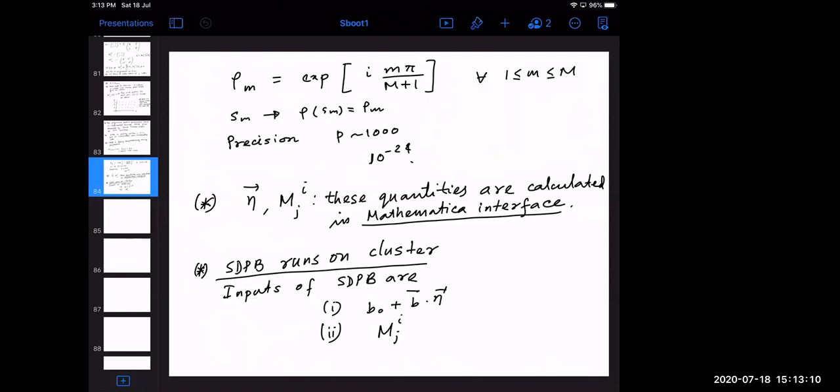Of course, this is an observation, so there's no concrete reason; they could not show why this is happening. For Lmax less than Nmax, the convergence was problematic, and there was some kind of numerical instability. Their suspicion is that for numerical stability, Lmax has to be at least equal to Nmax.